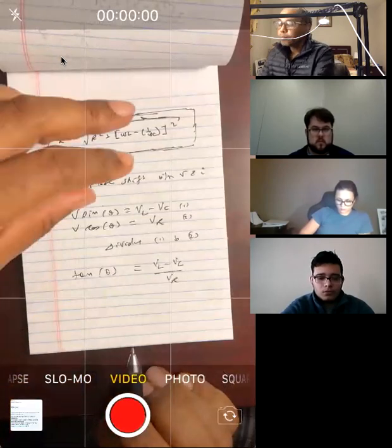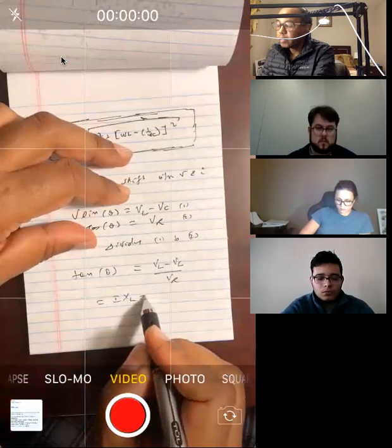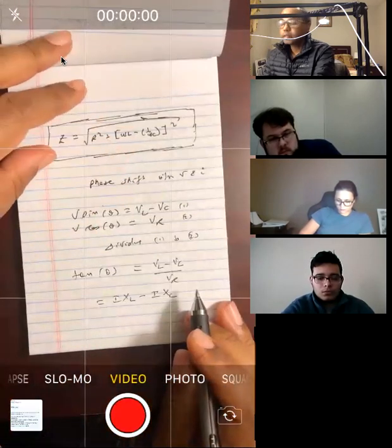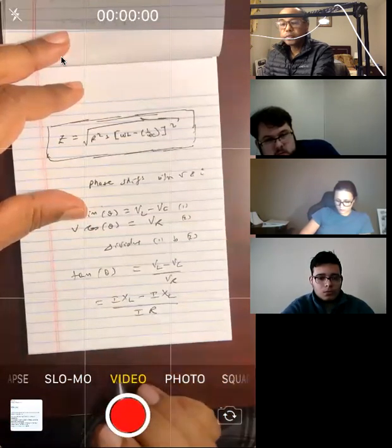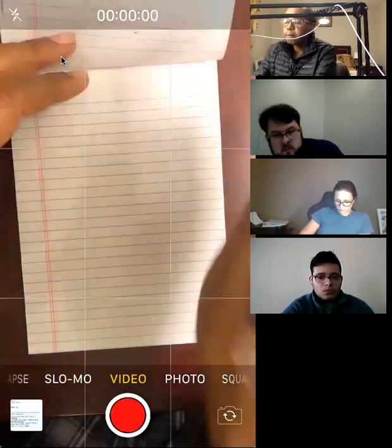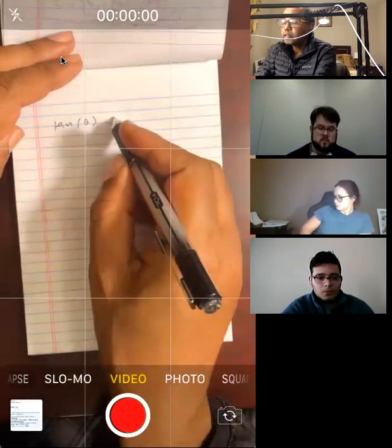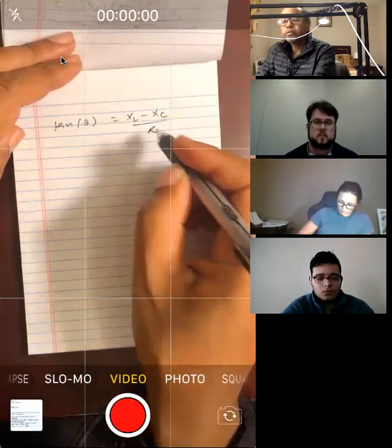Now, we know that VL is current times XL, and VC is current times XC, which is the capacitive reactance, divided by current times resistance. So that reduces to tan theta: the tangent of the phase angle is XL minus XC divided by the resistance.